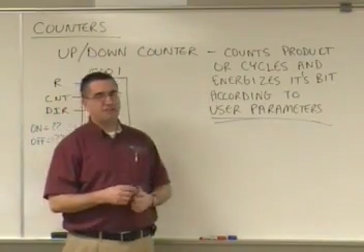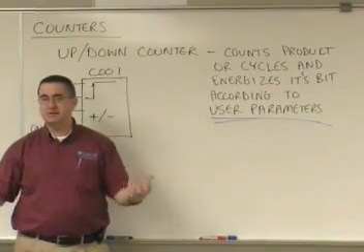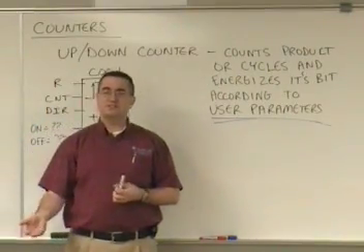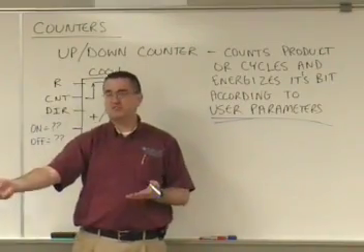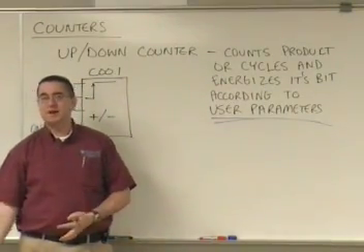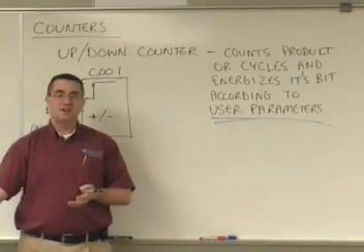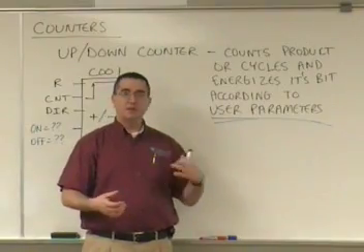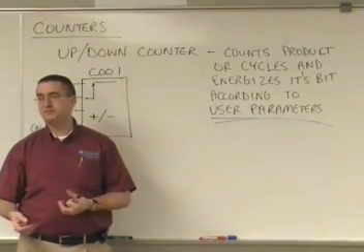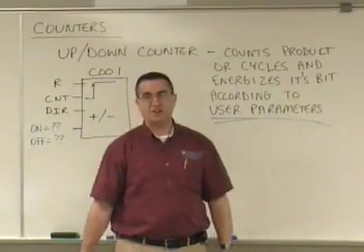Cycles I was talking about there. Let's say I'm running a motor, or an assembly line. Every time I start that system up, maybe I want to count that as a cycle. And maybe once I've cycled this system 1,000 times, I want to do maintenance on it. Or maybe when this motor has been energized and de-energized 1,000 times, I need to grease some bearings somewhere or something like that. So that could be cycles or products. There's lots of different things you guys can count.